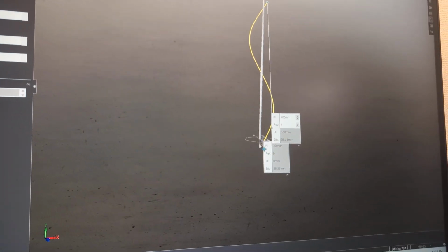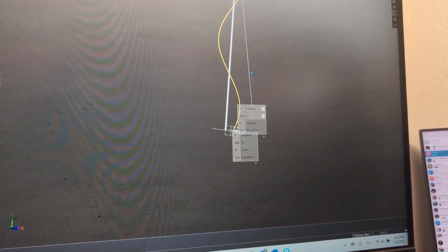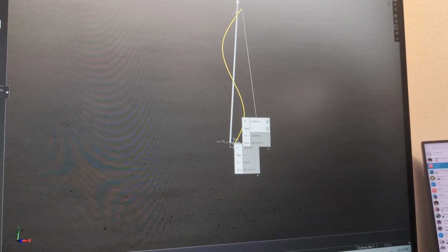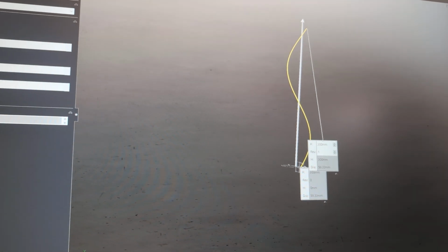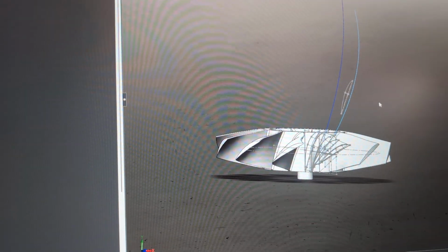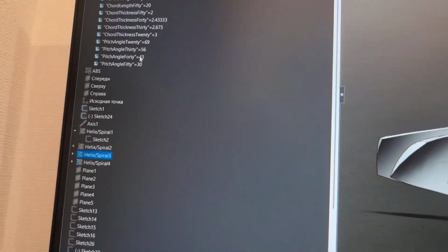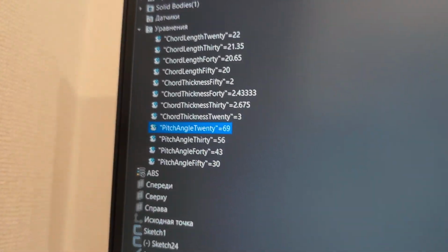That means that for 1 rotation of the propeller, the air will travel 300 millimeters, which equals some kind of degree. You can just calculate that angle. One time I was using inches, the other time, like right now, I was just using angles, like this, for example.